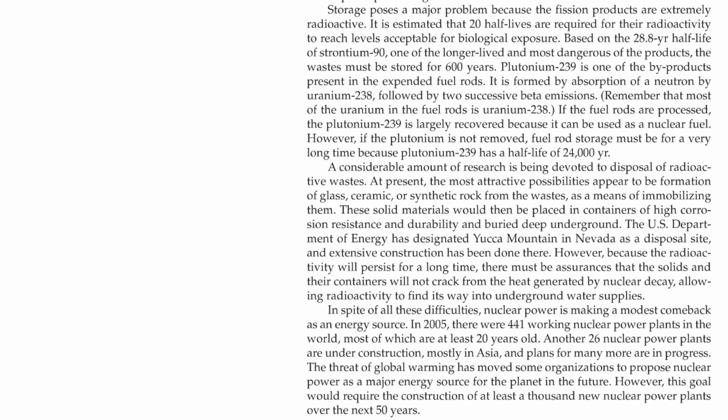A considerable amount of research is being devoted to disposal of radioactive wastes. At present, the most attractive possibilities appear to be the formation of glass, ceramic, or synthetic rock from wastes, which means immobilizing them. These solid materials would be placed in containers of high corrosion resistance and durability and buried deep underground. The U.S. Department of Energy has designated Yucca Mountain in Nevada as a disposal site, and extensive construction has been done there. However, because the radioactivity will persist for a long time, there must be assurances that the solids in their containers will not crack from the heat generated by nuclear decay, allowing radioactivity to find its way into underground water supplies.